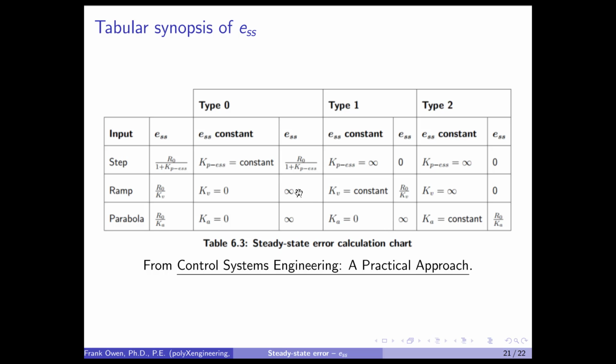So the system is not sophisticated enough to handle the complication of the complicated input. And by the same token, over here on the other side, we have complicated systems with simpler inputs. So in the upper right-hand corner, you will have zeros for your steady state error, and in the lower left-hand corner, you'll have infinity for your steady state error.